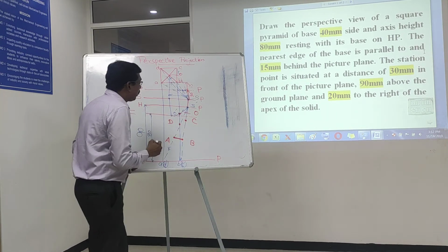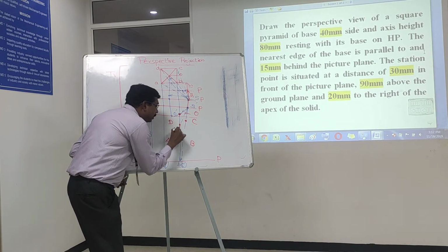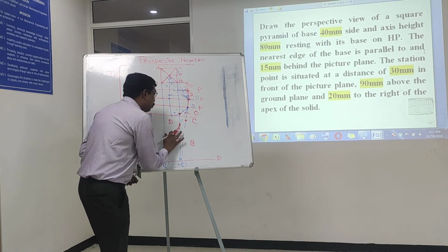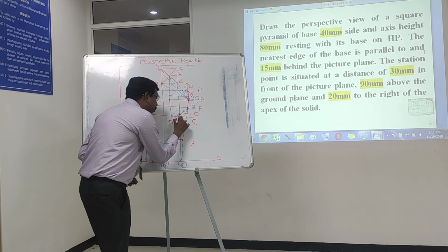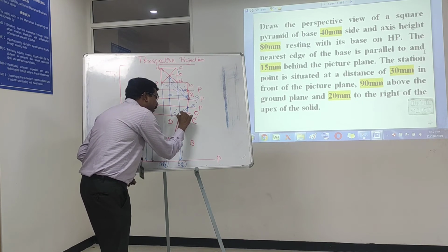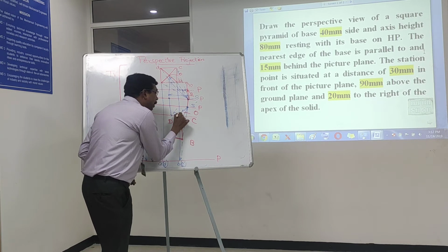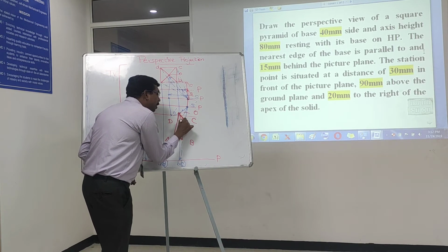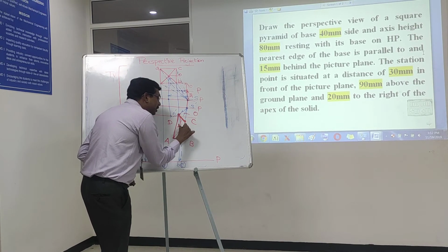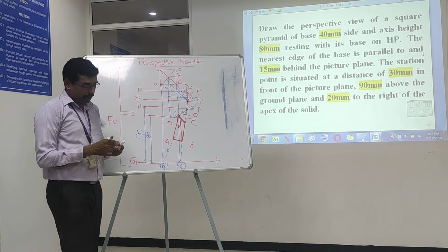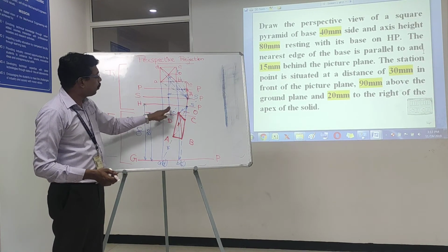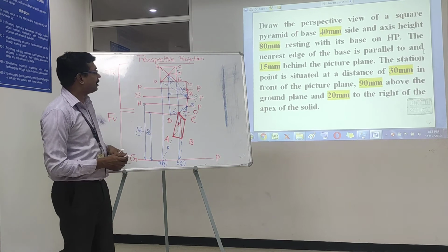So we have to mark AO in a straight, continuous thick line, and similarly OB and OC need to be drawn in a continuous thick line, right? Similarly CB, right? So look at the picture here. That is, A, B, C are visible, and similarly AO, BO and CO are visible, right?